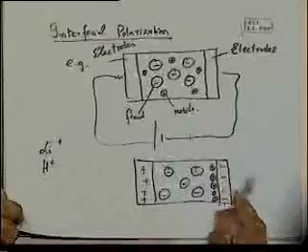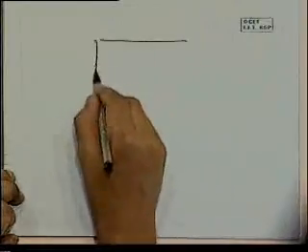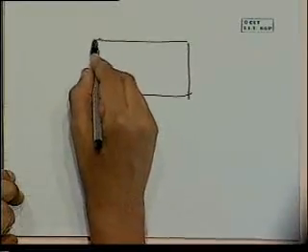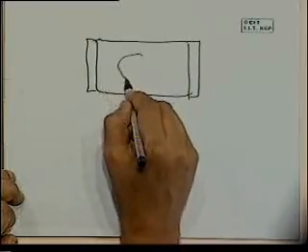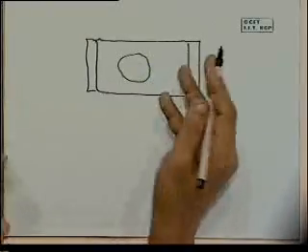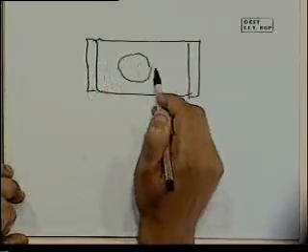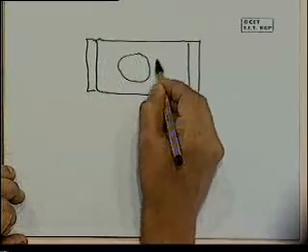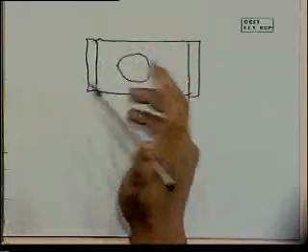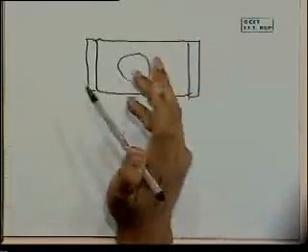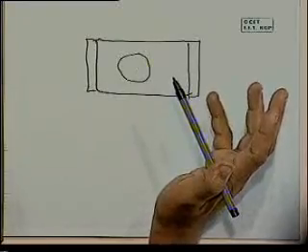Another example of how interfacial polarization might work is, let's say again you've got a material between two electrodes, except that there is, say, another grain. There are two grains there. So this is a grain boundary, or some other kind of phase, a two-phase material. Again, the same problem comes, that when it gets to this boundary, it's stuck. So even within the material, without even going out to the electrodes, we may end up with charge buildup.